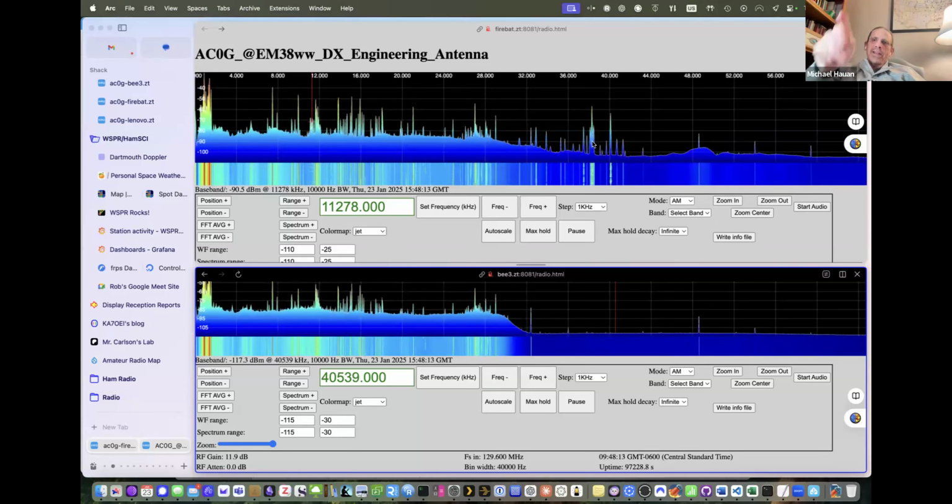One of them is I can put in the frequencies where I see what I suspect is an alias and use that, based on the sampling rate, to predict what frequency of transmission might be causing the alias. And the other way around is to put in the known local FM radio frequencies and then, knowing the sampling rate, predict where an alias might show up, which is kind of useful when you're looking at one of these things and you see weird signals and you wonder what they are and whether they might be an incursion of an alias.